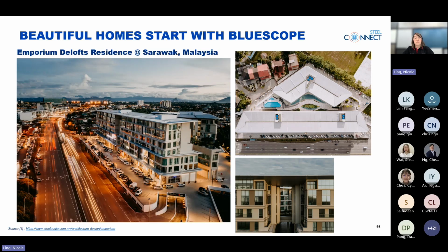This mixed development project is designed with two long linear building blocks with low pitch roof planes. Steel roofing allowed this roof to remain shallow and continuous. From the facade, the roof reads as a single neat line that ties the two buildings together. Rainwater is directed inward to a concealed central gutter, keeping the roof edge and facade visually clean. No downpipes can be seen on the outer building.